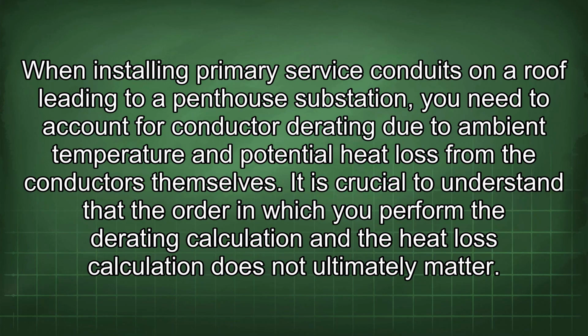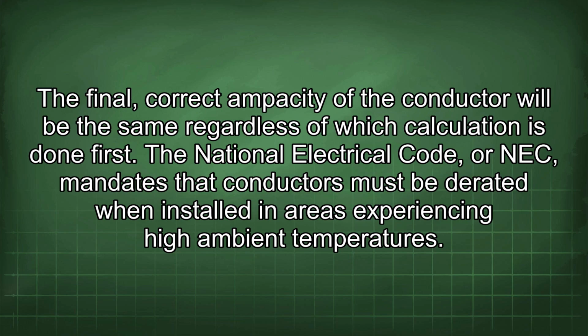When installing primary service conduits on a roof leading to a penthouse substation, you need to account for conductor derating due to ambient temperature and potential heat loss from the conductors themselves. It is crucial to understand that the order in which you perform the derating calculation and the heat loss calculation does not ultimately matter. The final, correct ampacity of the conductor will be the same regardless of which calculation is